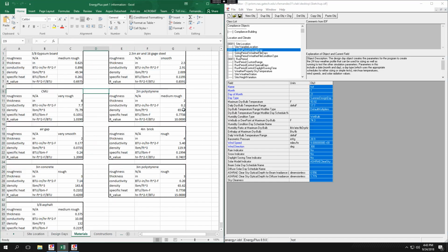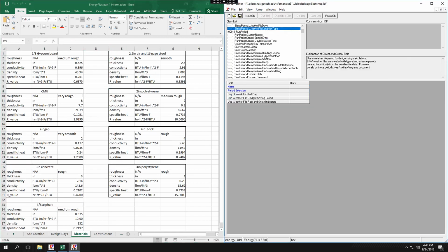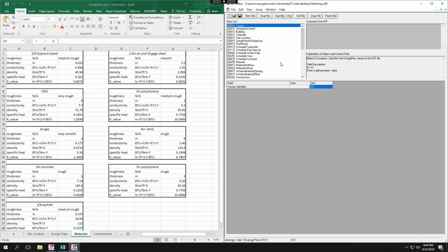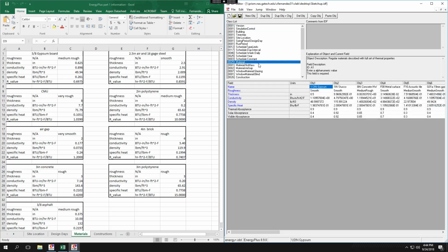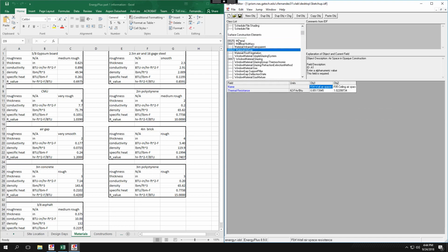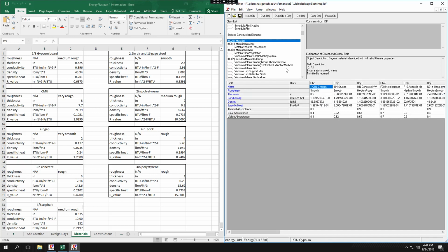So once you do that, we're going to go to materials. There are quite a lot of materials, but there are already materials in here. So if you want to condense it, you can hit Control+L, and that'll remove anything that does not have an input. So if we expand out, we'll see, none of these, we'll find this one, this one, this one. This number refers to a number of different objects in each thing. So as you see, when we condense it down, those go away.